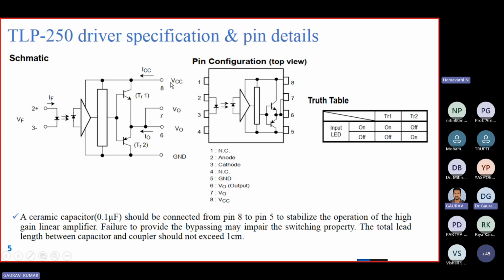And the 15 volt supply or 12 volt supply we can give to the 8 and 5 terminals of this TLP250 driver.